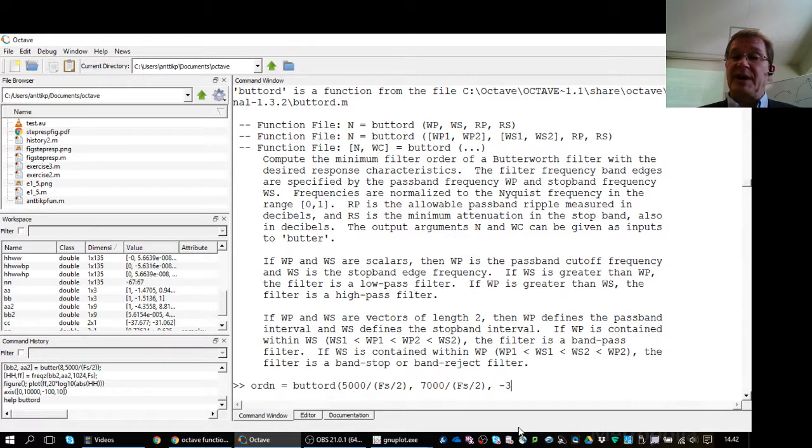Then minus 3 dB design point. Let's see, ripple. Minimum attenuation. Talking about attenuation, in this case it should actually be a positive number. The gain would be negative attenuation. Let's use it without a sign. So that means minus 3 dB point, 3 decibel ripple. And also attenuation is a positive number when it attenuates. Gain would be negative decibels. Remember this relative kind of thing.